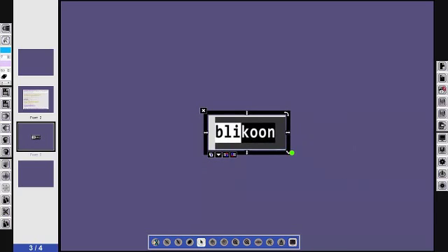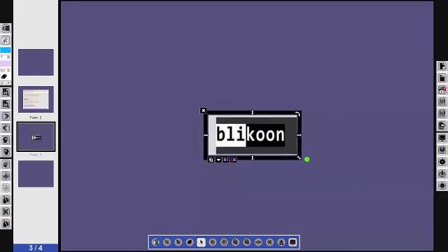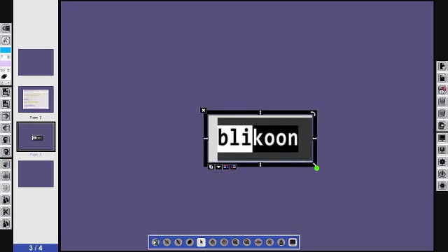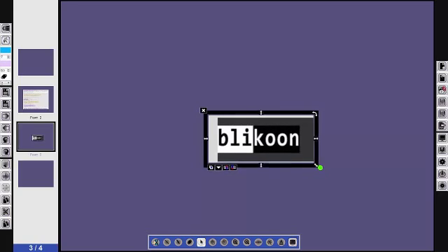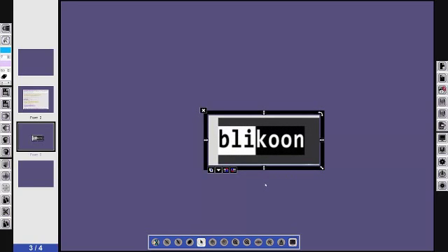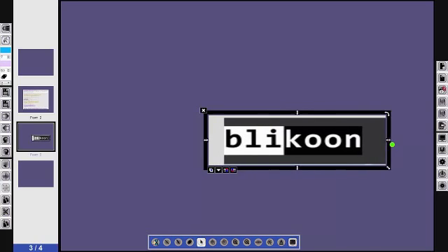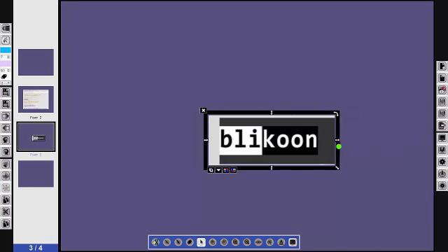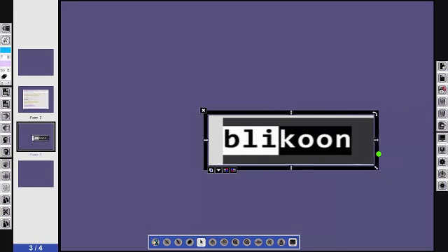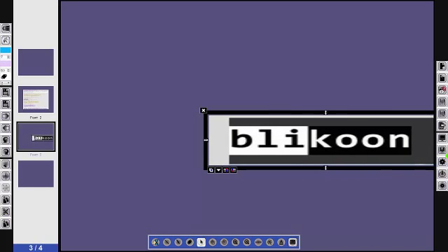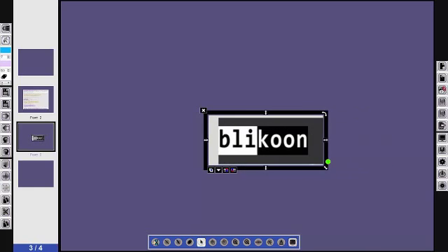This circle tells you that at that moment you can click down, hold, and move in the direction you want to increase your document. For example, here I increase the size of our image, keeping the relationship between the width and the height of the image. The same way, if I come here on the right, I see the green box, I click down, and I can change the size. This breaks the relationship between the width and the height of your image, and you can see that it starts getting distorted.